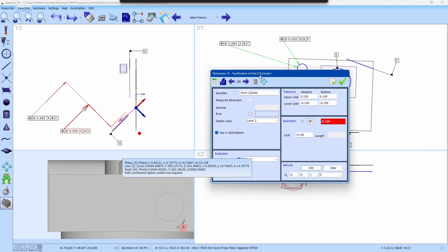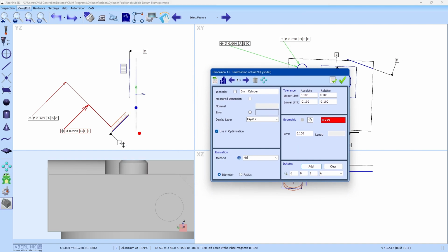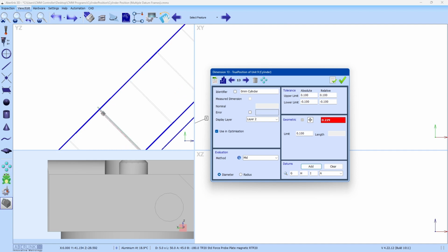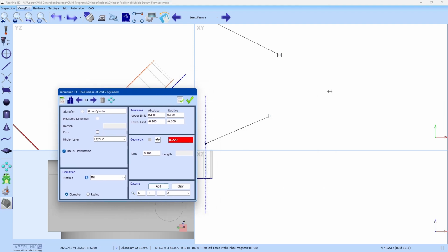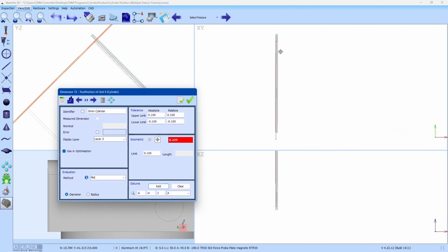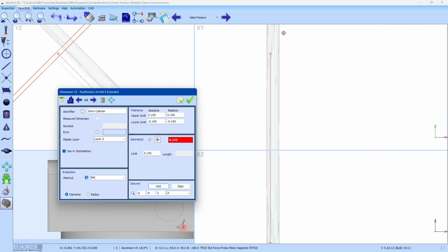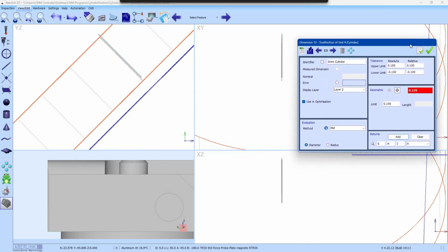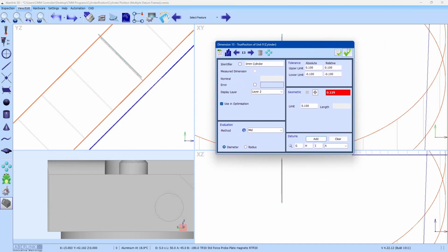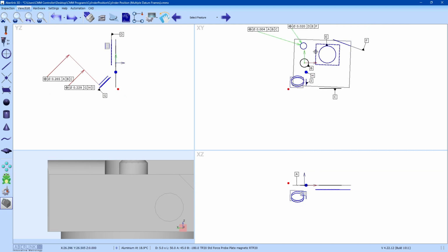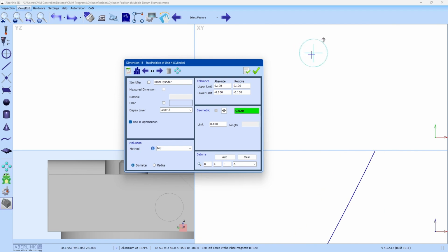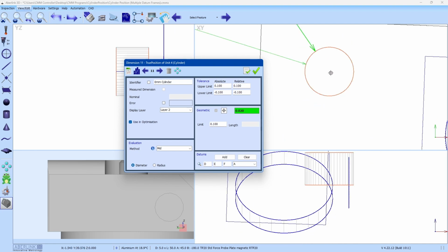It's also worth noting you do get a visual of the cylinder assessment. So we have the target zone and the line running through it. A little bit trickier to see here. So this is a visual ID of the line of this axis cylinder versus the nominal. And you'll see because it's outside of that window, it's showing up red visually. This was the same for this cylinder. You can zoom in and see the target zone versus the actual. This is displayed as soon as you right click the dimension.